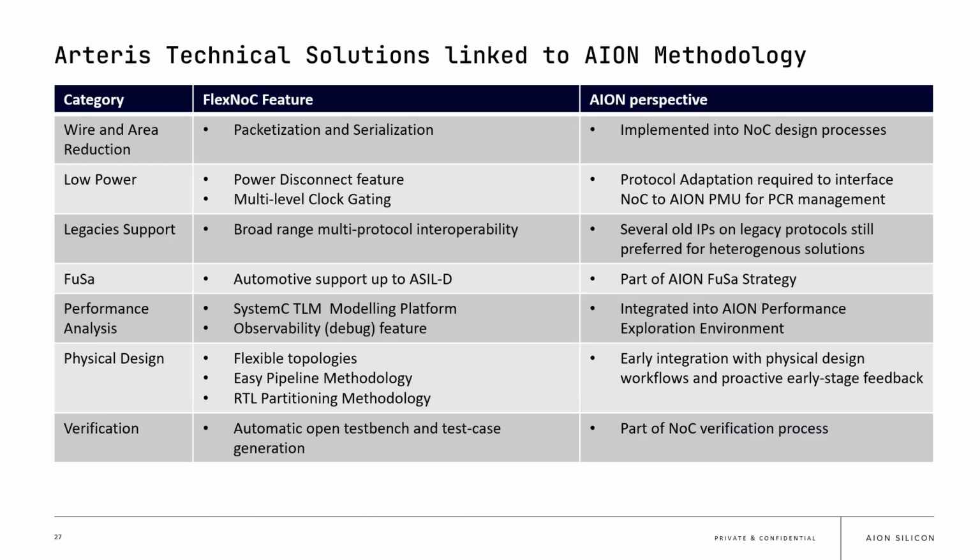Thanks for that, Andy. So now I'll cover briefly how Arteris technical solutions are linked to Aion's methodologies. In terms of wire and area reduction, we've got the packetization and serialization features, which have been implemented into the NoC design process. And also on low power, we've got the power disconnect feature and multi-level clock gating, which we've implemented as part of the platform management unit and power clock reset strategy.